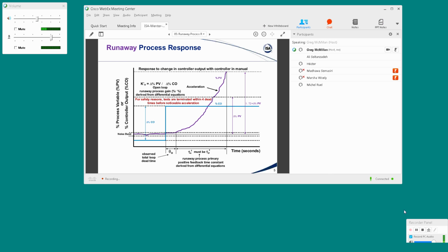Coming back to the distinction between lambda tuning and lambda tuning for near integrating processes, which are in fact two different animals, with two different sets of formulas. It's coming mostly from the computer industry. They like to look at set point change, not load change. Right. And really the lambda tuning rule was developed for, I would say, a nice landing, not a nice takeoff.